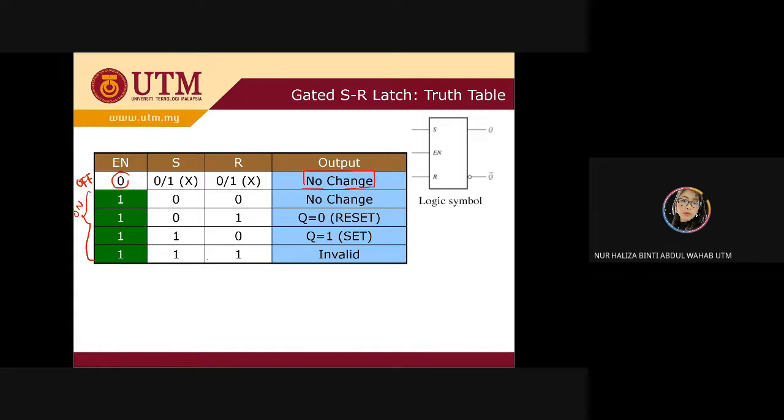So your truth table here: if you have 0, 0, it's similar to your SR latch, no change. If you have 0, 1, it will be reset.